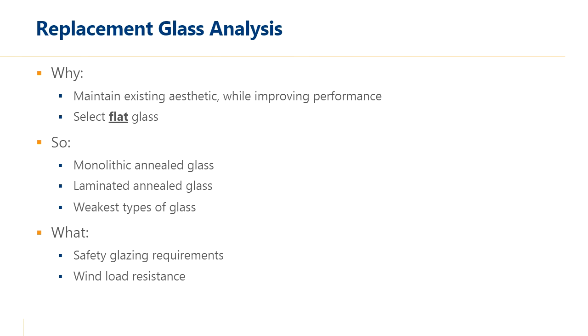Modern codes like the IBC require replacement glass to meet current standards for new glass. So that means ostensibly that you would need to design for modern wind loads. If that's too onerous, perhaps you can get a variance, but in either case, analysis for wind loads is relatively easy using ASTM standards and available software. What's a more difficult characteristic to analyze of the weak annealed glass is its thermal load resistance.